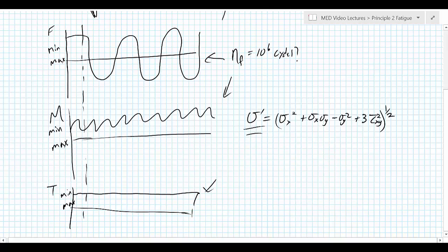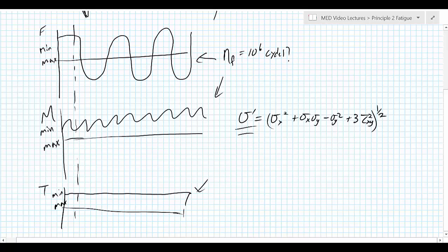In this situation, our torque mean and maximum are the same thing. This is effectively static loading at that time scale. For the bending cycles, the axial load basically looks like a constant load. And then for the mean bending stress, we have one cycle. So in general, we'll take the smallest cycle we can and evaluate the loading over that.